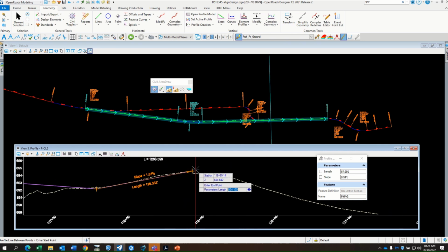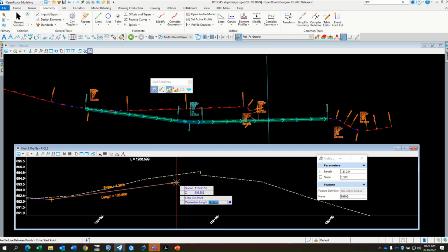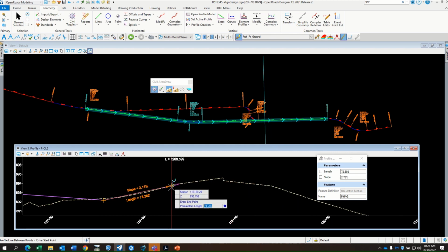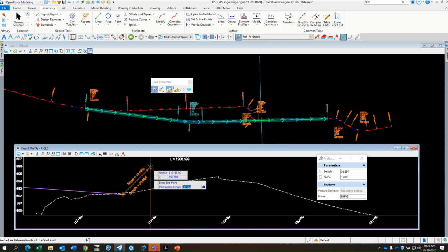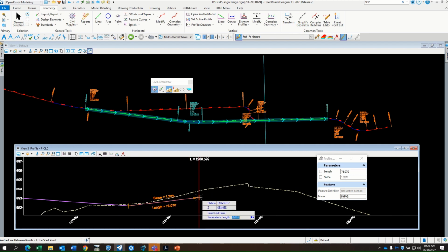I'm looking at this, and why are you seeing this craziness? It would have to do with, if you look back at the survey, when the survey was processed, the shots that were taken, the existing terrain probably needs to be cleaned up a little bit. There's some kind of shot here that was off, and that may or may not be within my limits. And of course, the density of the survey becomes very important also, I would say, with OpenRoads, because you do end up with segmented items, and then you might be tying into some station that you don't really want. So in many cases, it's more ideal to be more densified in our shots.